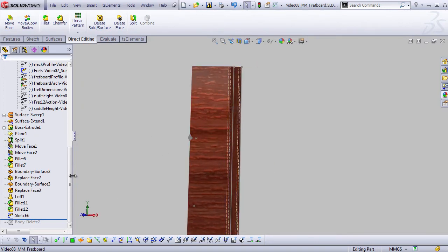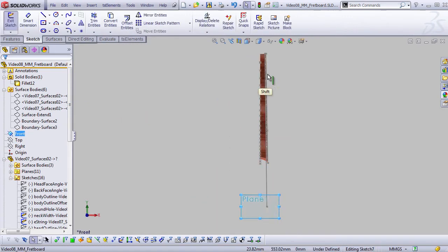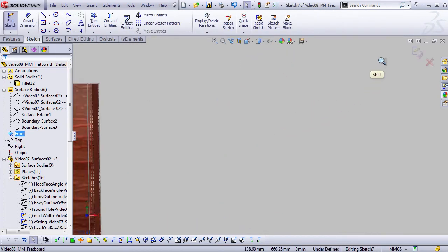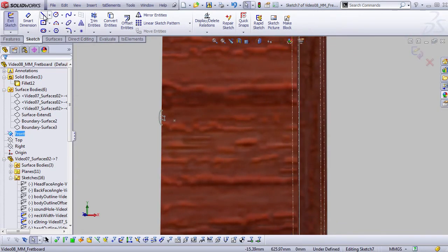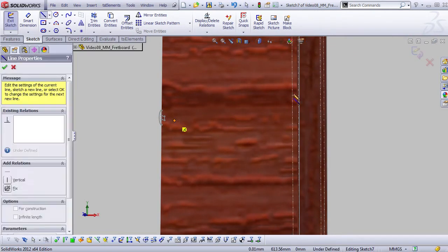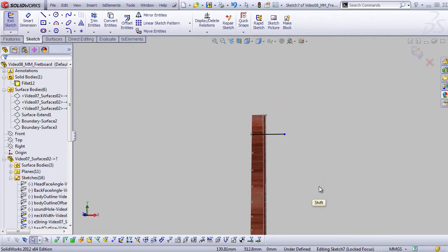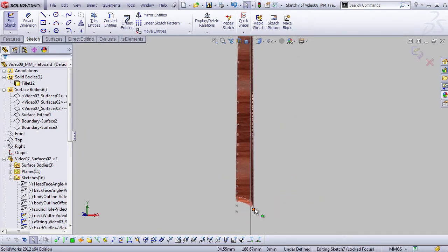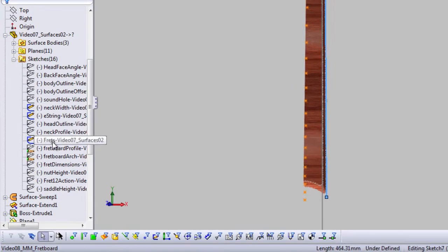Next, we're going to create another sketch. Let's go to the front plane and create another sketch. Zoom back in here where our first fret position is. Grab the line tool and just drag a line, or click one end of a line and then click another one way on out here, perfectly horizontal. And one other thing, you want to make sure that this sketch is showing. This sketch, if we look in our original import here, it happens to be this sketch, which is the neck